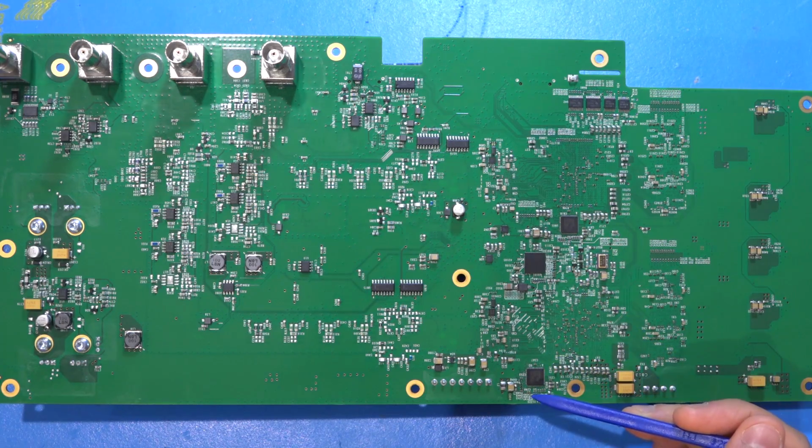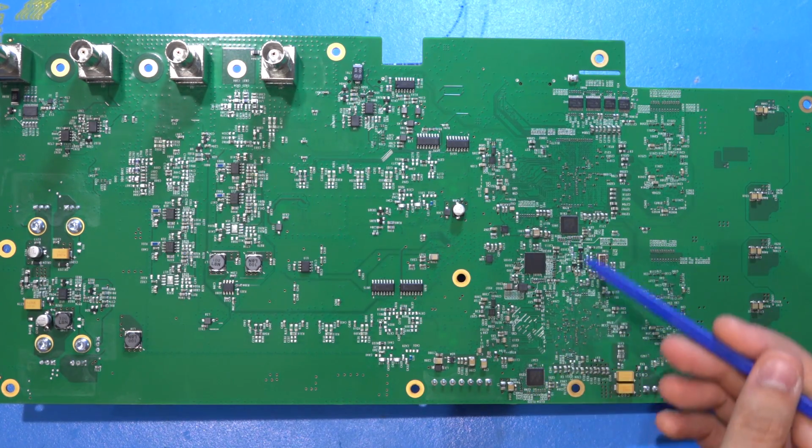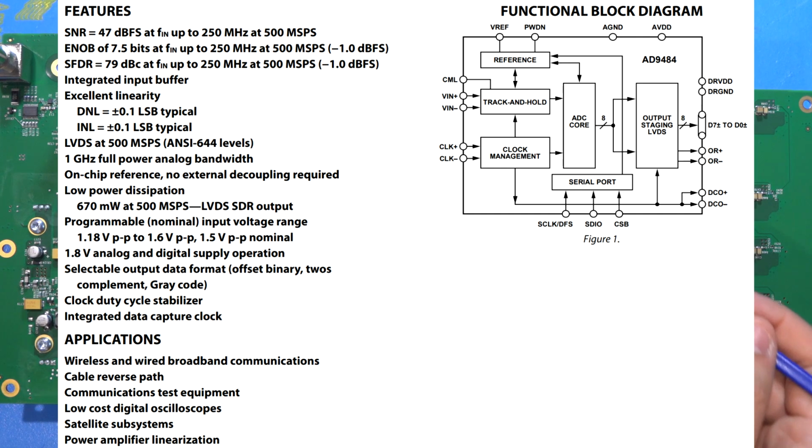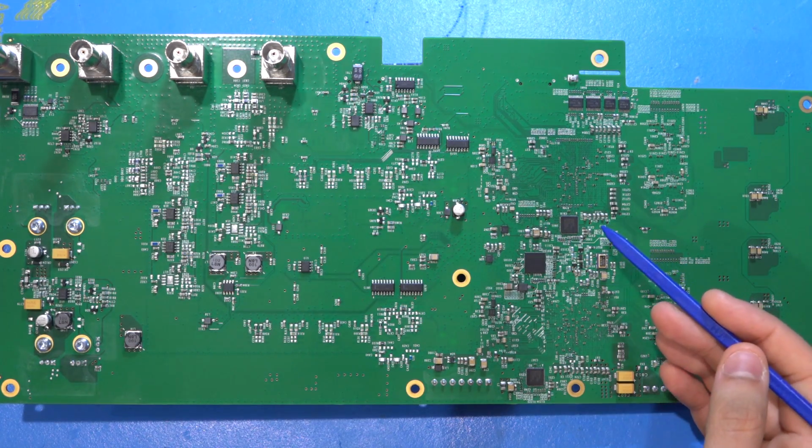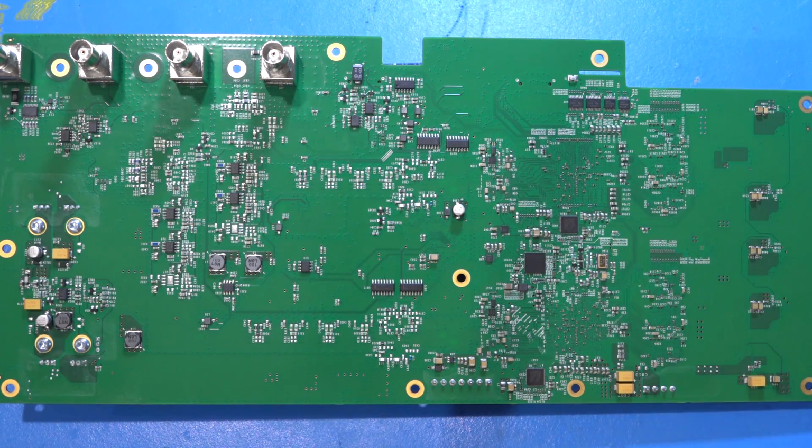These are 8-bit 500 megasample per second Analog Devices AD9484. And there's two of them because we have two channels. And I believe this is what finally closes the loop on the InstaView circuitry in combination with potentially those TIC chips I was talking about earlier. What is a little bit surprising is how far these are from the output. But again, you have only two ways.